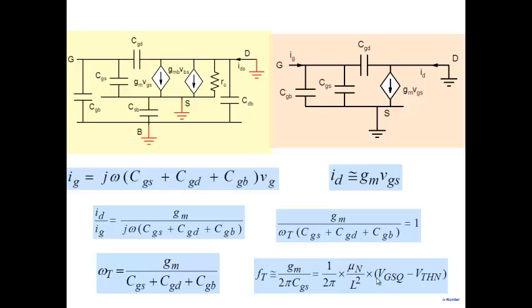But there are problems. The reason why you don't see those kinds of MOSFETs is they have their own problems, and silicon MOSFETs are still dominant. So mobility is an important part, but a much more important part is what you see is L. You make a MOSFET faster by reducing its channel length.